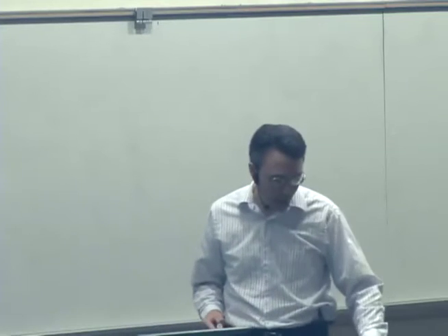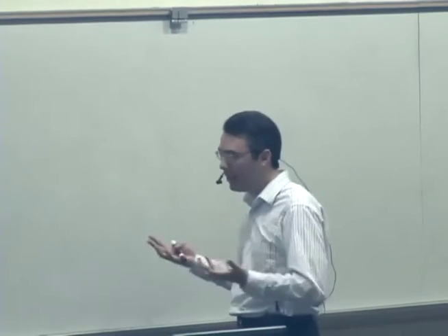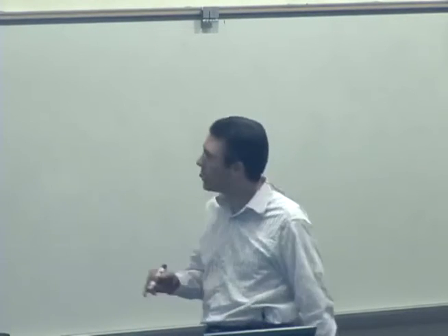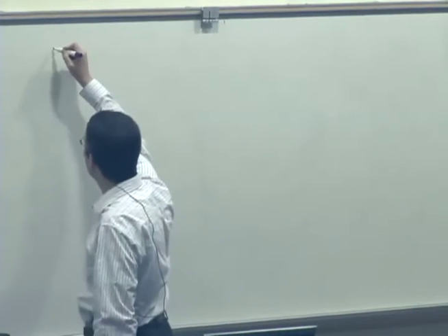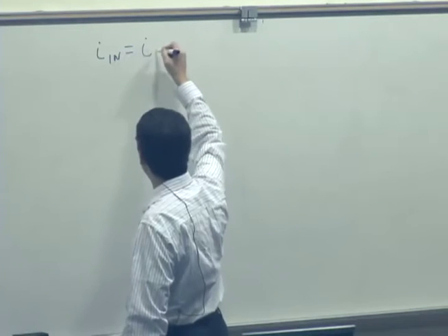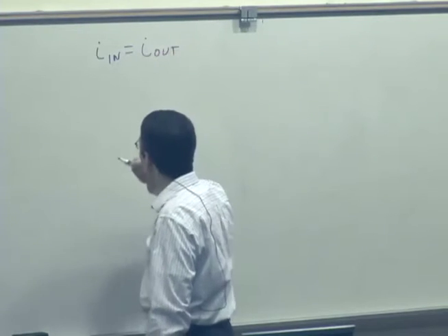Circuits. We talked last time about the mechanism behind creating electric fields in circuits, talking about surface charges on wires and surface charge gradients. And I'm going to talk about now another tool for analyzing circuits. We've talked about the basic principle of the node rule, or current conservation, saying the current in is equal to the current out of a particular point of a circuit.